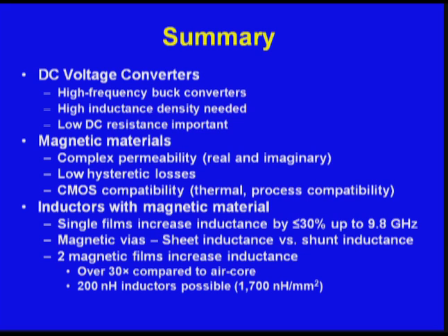Hysteresis is very important. And then a whole area that I didn't touch on at all, but if there were more material scientists, I have probably another 15 slides I could show you, is that it really needs to be CMOS compatible. You can't just throw something on there and expect it to stick and be able to pattern it, be able to make the oxides in the lamination, have the deposition process be reasonable, be able to deposit dielectrics over it, have the dielectric stick, and pattern that as well. There's a lot of issues.